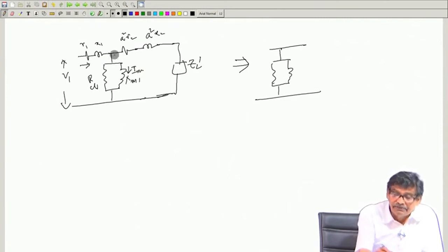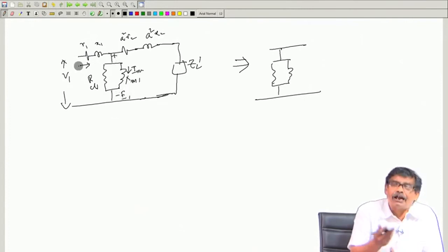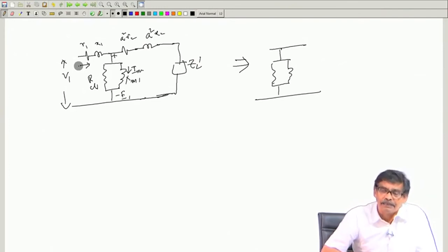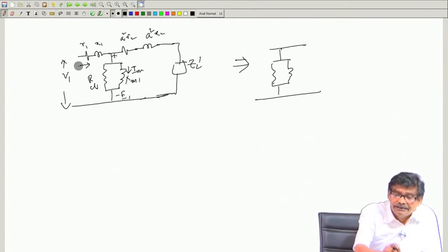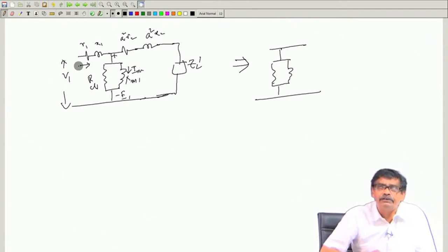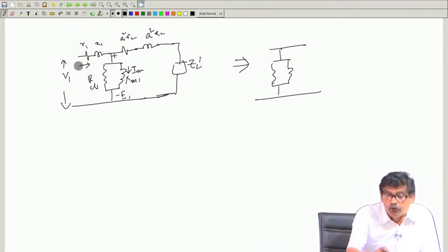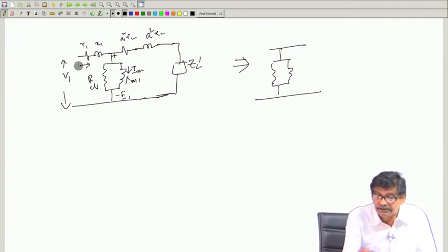Now, what is the difference between this voltage and this voltage? This is E1. It is this drop, but R1 X1 is small. Even when rated current flows, when you have connected load, there will be little drop here, that will definitely decrease your phi. Phi max is E by 4.44 f N, is it not.